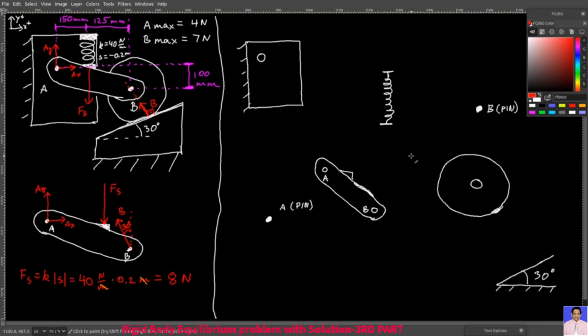Welcome back. What I want to do now, I want to take this entire structure and disassemble it, and I want you to see that when this structure is in equilibrium, how exactly the forces get transmitted through this mechanism. Here you see Newton's third law at play. We assume that the surface that the wheel rests upon is solidly fixed, and the same thing can be said about this part here that is fixed to the wall. Let it be our fixed plate.